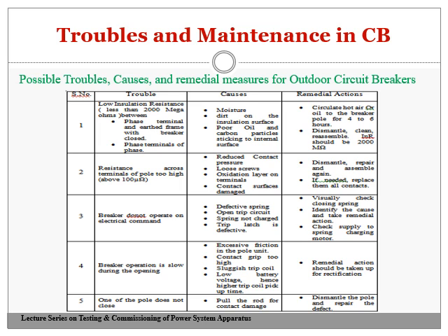Now, how to remove that? The remedial measure to increase the insulation resistance, or remove the moisture content, is done by circulating hot air or oil to the breaker pole for 4 to 6 hours. That is the drying of the circuit breaker. I can say it is blowing hot air across the complete circuit breaker so that you can remove the moisture content which might have been absorbed by the insulation used in the circuit breaker. Or you can dismantle, clean and reassemble; the insulation resistance should be this much, 2000 mega ohms.